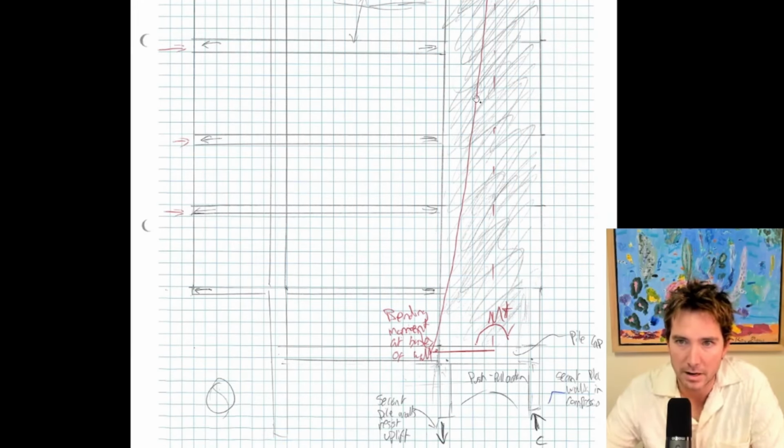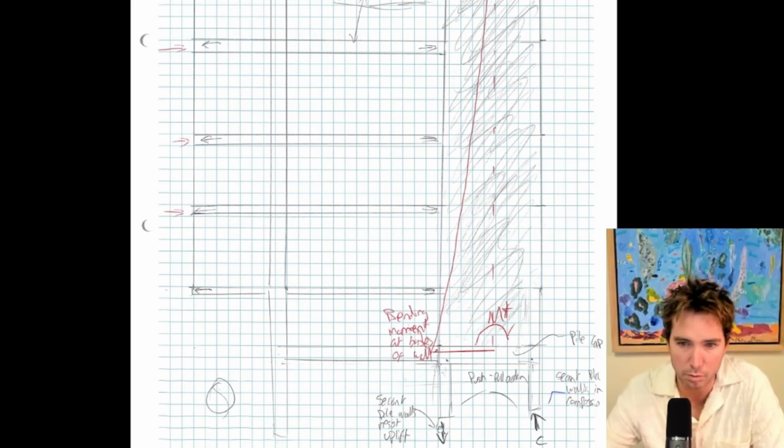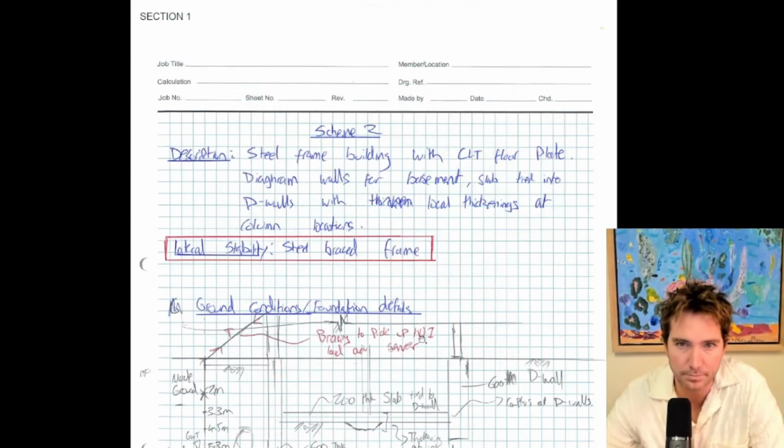So my concrete shear walls act somewhat as a cantilever, with max bending moment at the base, and that's resolved through my pile with a pile cap through some push-pull actions. I'm not doing any actual numbers here. I'm just demonstrating how the loads get to the ground.